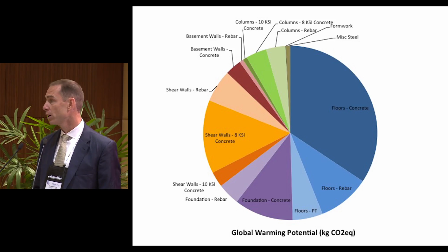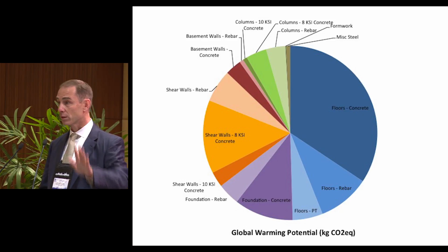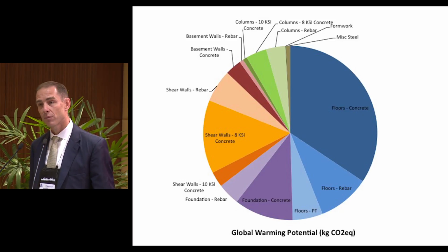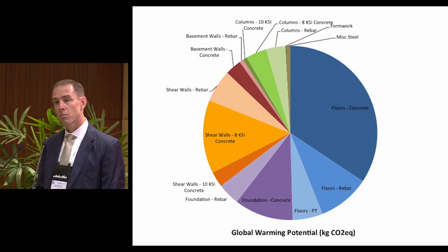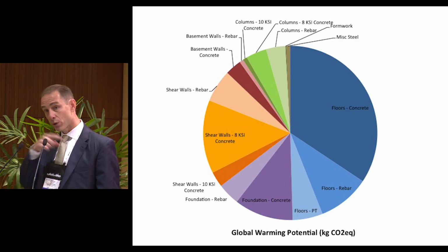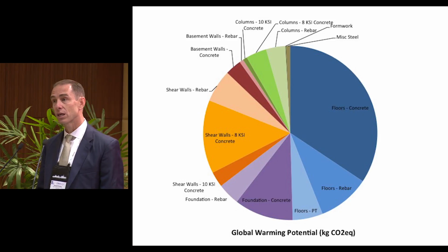Well, I'll just talk about the rest of the results then from there. What you're not seeing here, though, is if you saw the pictures from the Lumina project in San Francisco, actually on this project there was a significant difference in the embodied carbon of the concrete and the rebar between Tally and what was actually built. And part of it is regional. In Seattle, we have a great aggregate supply, and so the mixes can be tuned up a little bit more. Part of it has to do with, frankly, quality control and consistency of the batch plants that are supplying the mix. The rebar in Seattle that went into that 2030 project also has some unique characteristics.